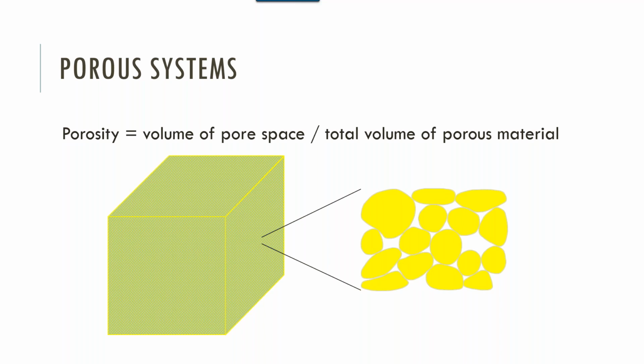So in an aquifer, a sand and gravel aquifer in particular, if it's 100 feet thick and it's full of water, if you took all the sand away, you'd still have 30 feet of water left, which is a lot of water. That's why sand and gravel aquifers, if you're on one, are usually pretty prolific. Most irrigation occurs out of those sand and gravel aquifers, where they can pump thousands of gallons a minute.